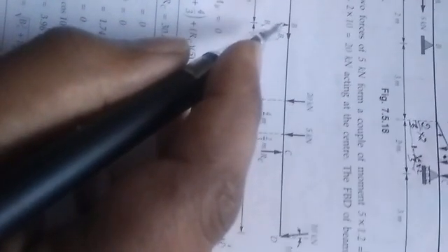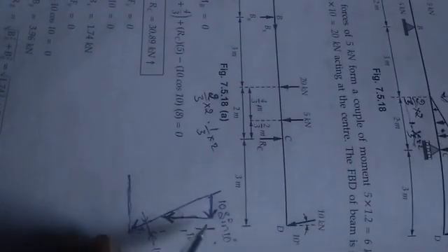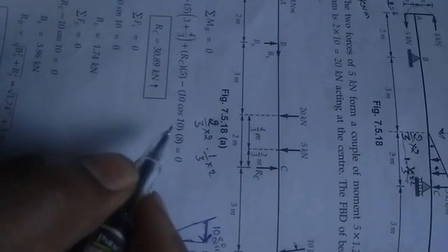But when you come here, you have to be very careful. The horizontal force will be acting here; if you take a line diagram, it comes here only, so no moment from it. So you take only the vertical force, that is 10 cos 10, acting here. 10 cos 10 into the distance, 3 plus 2 is 5, 5 plus 3, totally 8, so 8 into 10 cos 10.